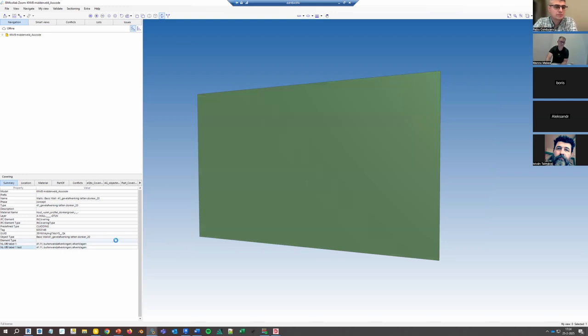And sometimes the description is in capitals or not in capitals. So basically it's a big mess, or there's a lot of differences, while it's actually quite easy to get it right. And that's why I like to add it in the element itself. So it's fixed in the element. And also because it's a parameter, you can set the parameter to instance in case you can nest it or use it in nested elements. So you can associate the parameter so it will inherit the classification code from the host. So there's a lot of advantages of doing that.